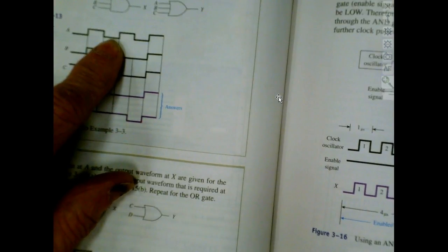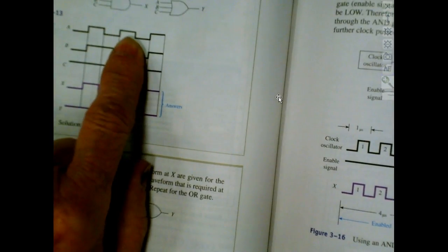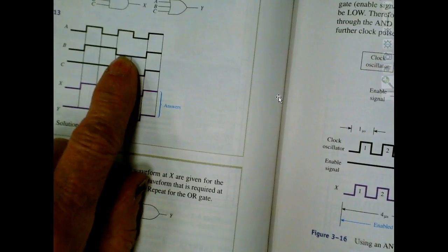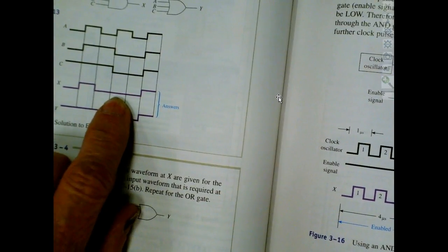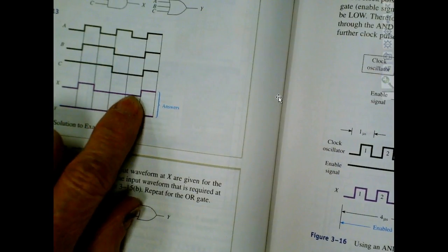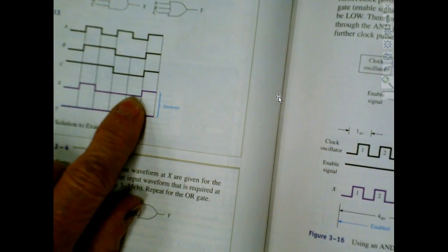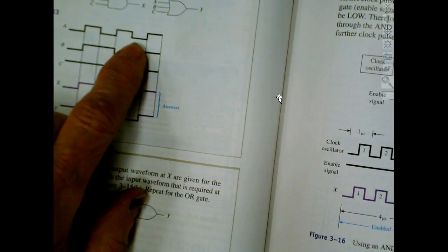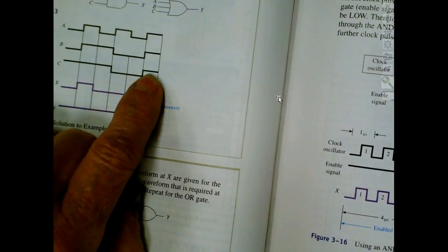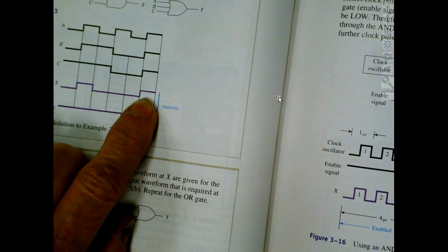Does that make sense? I look here. This looks like we're pretty good right there. Oh, but there's a low right there. As soon as I see that low, I'd put a low. I come up here. I start off with a low. So right off the bat, I'm going to put a low because it takes all inputs to get a high. Here I see this one. There's a high. There's a high. There's a high. So the output would be high.